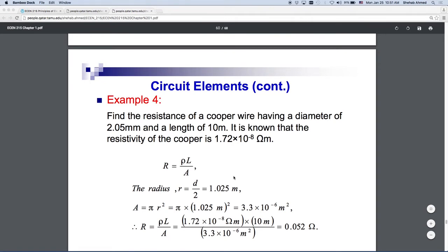So we talked about resistivity and how to calculate resistance of a conductor, and we said that the resistance of a conductor is equal to rho, which is the resistivity, multiplied by the length divided by the area of the conductor. So the larger the diameter, obviously, or the larger the cross-sectional area of the conductor which current is flowing through, the lower the resistance that we have, which is why you will find the overhead transmission lines, big cables without an insulating jacket around them, they're just hanging up there.